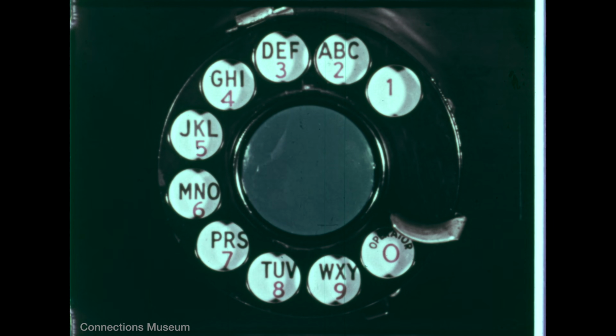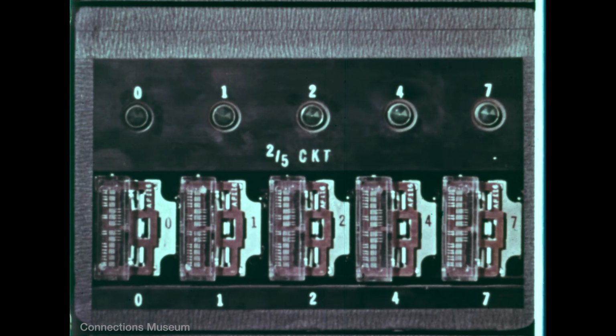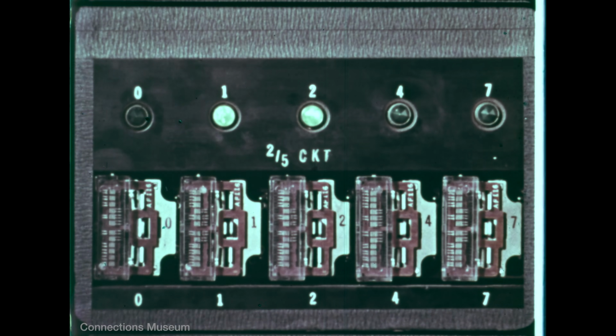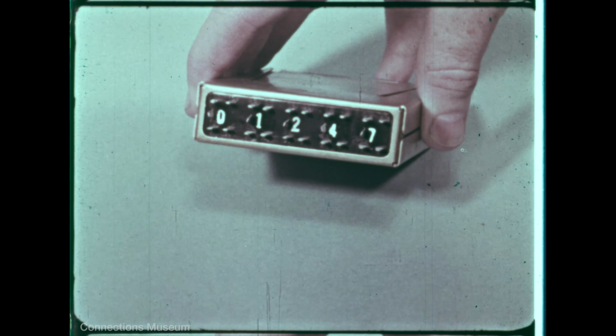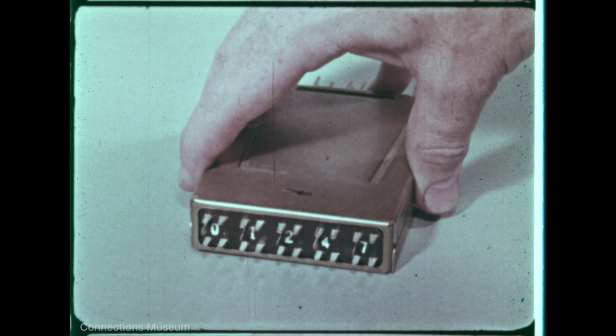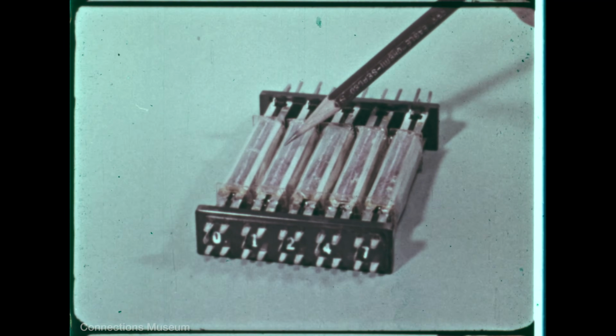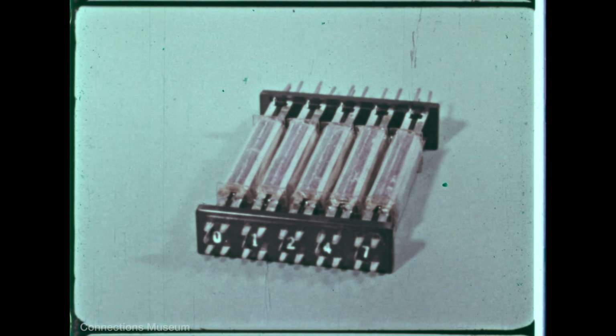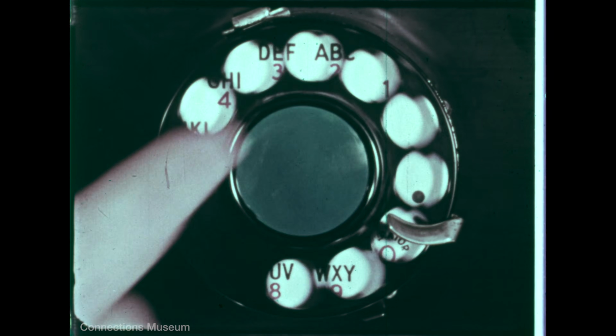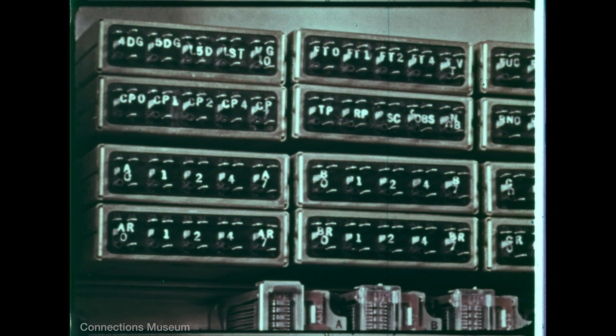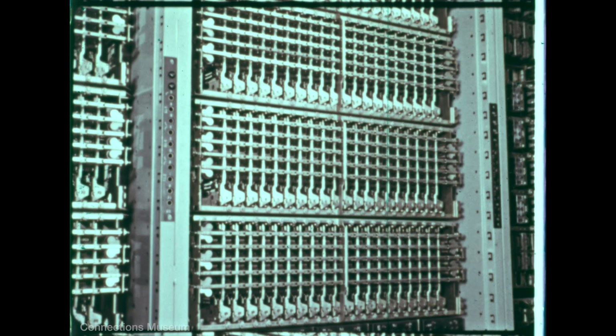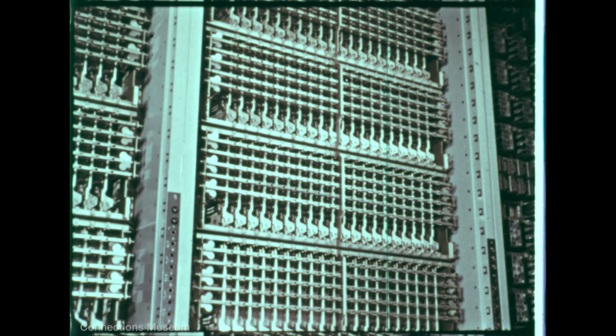Dialing the number 3, for example, will operate relays designated 1 and 2. If by chance only one relay operates, the system knows there is an error. From here, the digit is transferred to a package of 5 simple relays. 2 out of 5 code is used here also. Each telephone digit dialed is stored in its own package of relays in a bank. This information is used to control the crossbar switch, which completes the telephone connection.